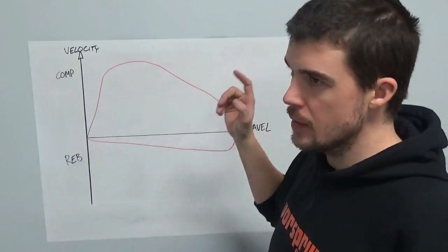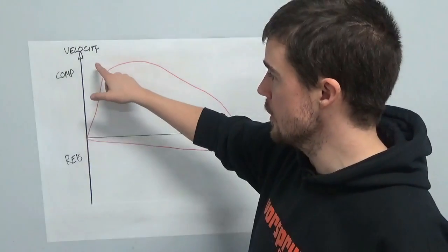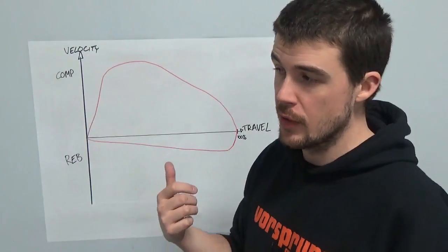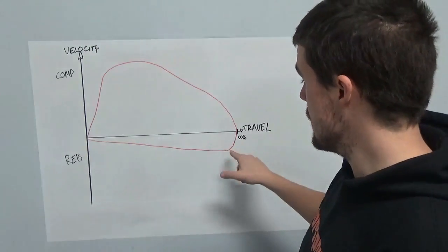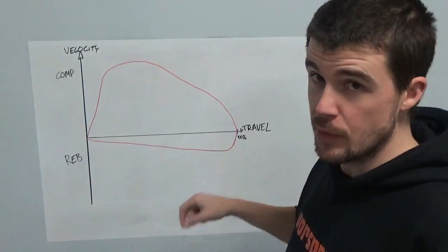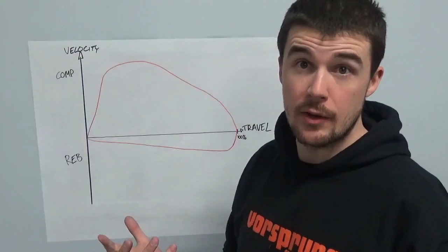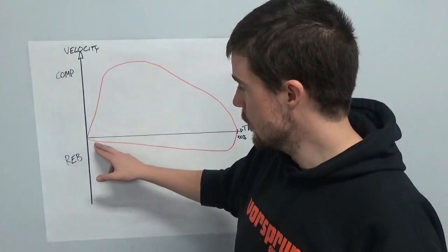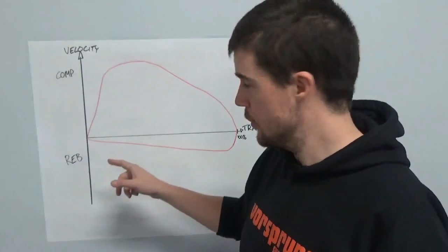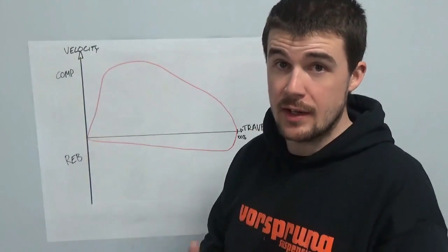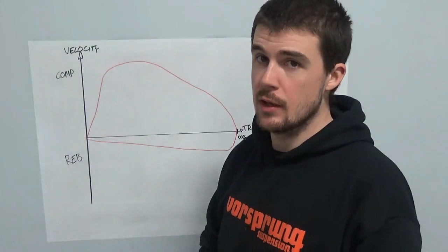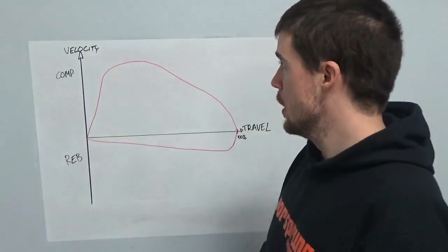So the reason for this is typically that the highest velocities are encountered when there is the lowest resistance, meaning the lowest spring force. And likewise in rebound, the highest velocities in rebound occur when the spring force is at its highest. So rebound peak velocities drop off as spring force drops off, because the only thing that is acting to extend the suspension is obviously the force of the spring minus the force of the rebound damping.